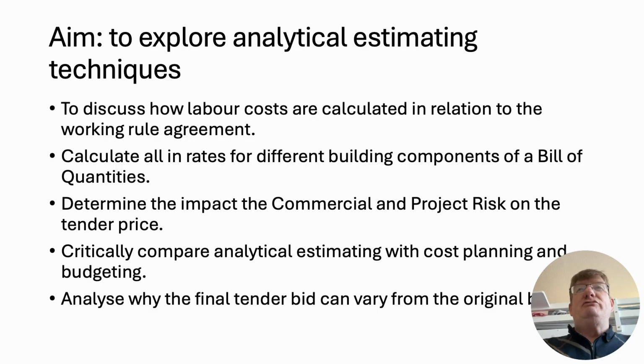So you're following these rules of measurement, particularly those in NRM1, and you're producing a cost estimate based on the GIFA, or a budget or an estimate based on the measurement rules for an elemental cost plan. Again, you follow the rules to produce an elemental cost plan with approximate quantities.